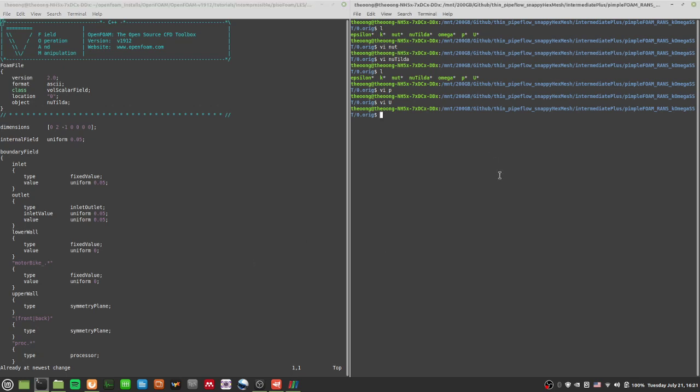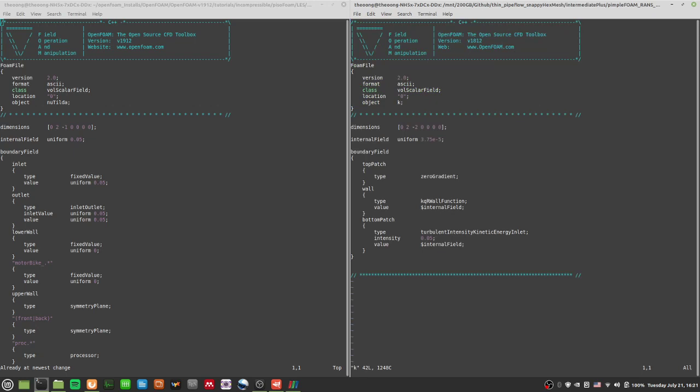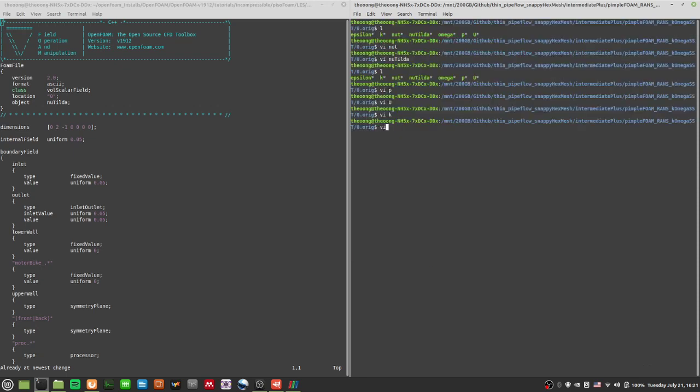As I was saying in the last video, we are doing some Spalart-Allmaras boundary conditions. Unfortunately, making Spalart-Allmaras boundary conditions is not as straightforward as the k omega SST or kEpsilon method. For k omega SST and kEpsilon, especially for the inlet, you can just specify a turbulent kinetic energy based on some intensity, and then OpenFOAM will just calculate everything for you. That's very convenient. And the same goes for omega and epsilon.